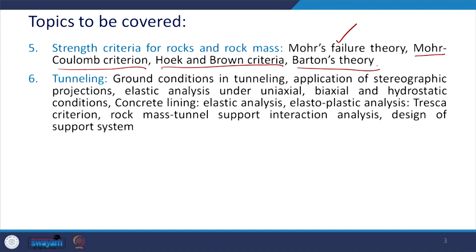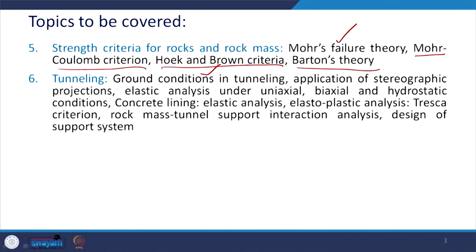Now, depending upon which area you have the project related to tunneling, you can have different ground conditions. So, we will learn about different ground conditions for tunneling. Then the stereographic projections, which we learnt in the second chapter, the application of that we will see here with respect to tunneling. Then elastic analysis of the tunnels under uniaxial, biaxial and hydrostatic conditions, and when we excavate, tunnels are to be provided with lining.